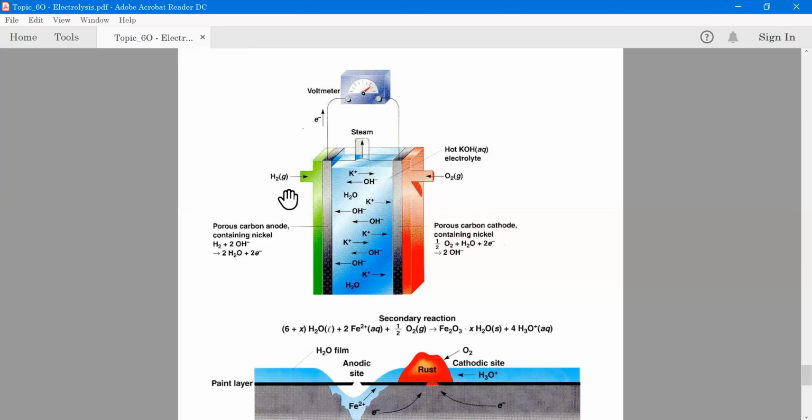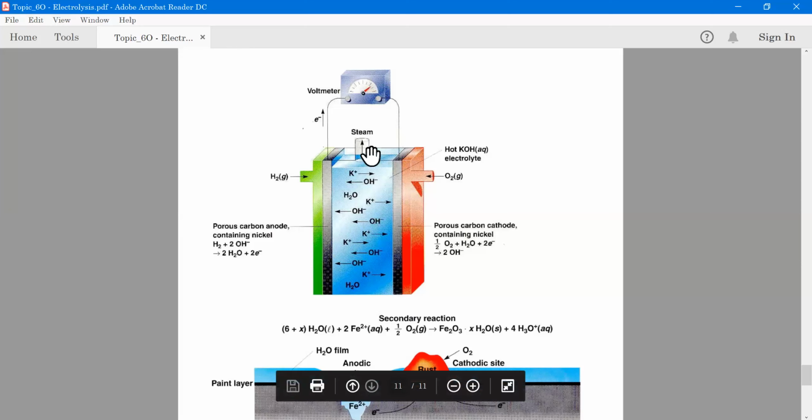It has to be properly contained, and that's part of the technology that's being developed: not have the hydrogen be a tank of compressed hydrogen, but rather have it contained in a solid that releases it as needed. And there is research being done to develop these hydrogen absorbing materials. And of course, they have to absorb hydrogen, but they also have to be sufficiently light that they're not adding too much to the weight of the vehicle. In any case, hydrogen oxygen fuel cells are an important technology that's being developed for vehicles right now.